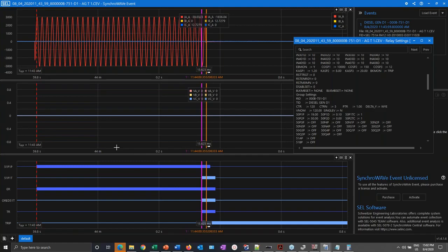You have to realize that there are differences between the time that the commands are issued and the digital signals appear inside the relay, and then you have 4 milliseconds, depending on the type of relay, of processing time, and then you have the test set, which also doesn't behave absolutely instantaneously. So when you put all those little bits and pieces of time together, you get this difference. In my opinion, it's 4 milliseconds of processing, 8 milliseconds of the mechanical trip, and 4 milliseconds for the current to die out on the test set. That's my interpretation of this case right here.